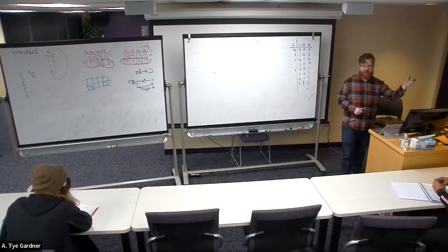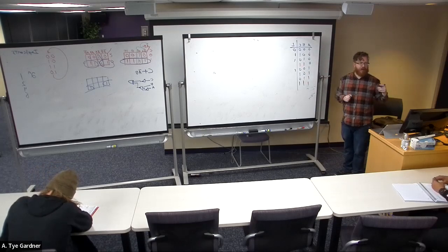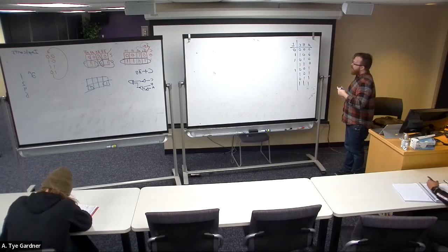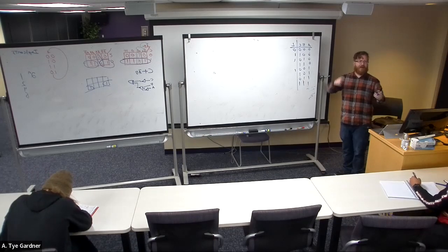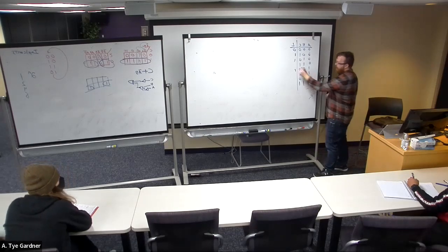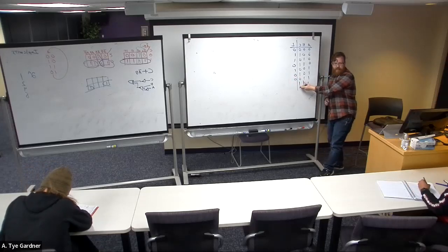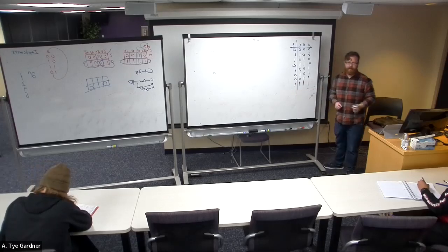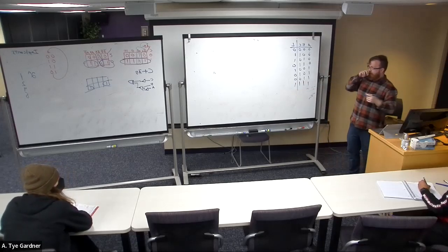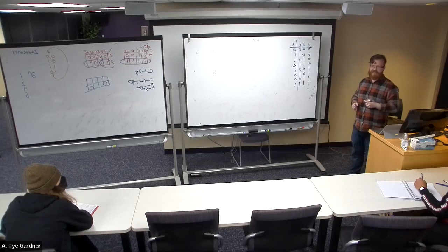I flipped any one of those, right? So this is just connecting this truth table to the physical story problem. Okay, and now any 2 of them, if I flick the other one on, it turns back off, right? Which is annoying. This is why we end up in these situations where the light switches are in stupid positions. Well, that's off, and that's off. And then we get a third one. That's the 1. So basically what we've done is we've ended up with an odd number detector. Right? That's all this really is.